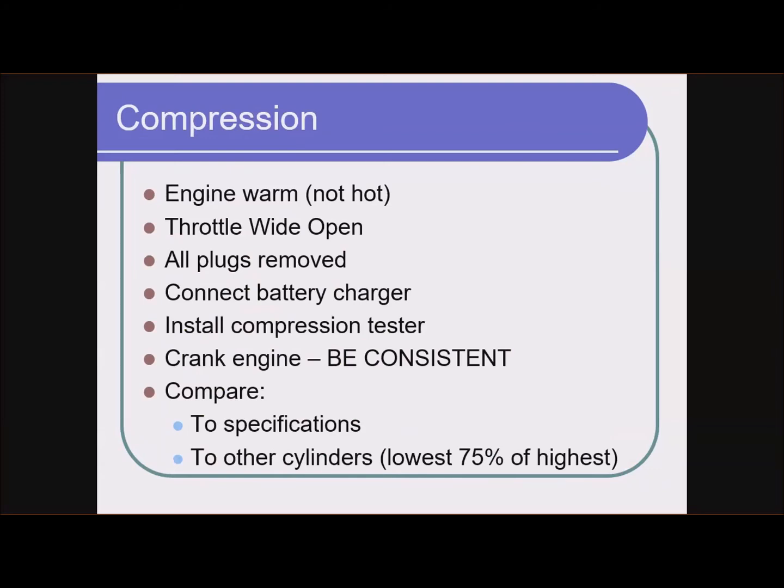So when an engine is at operating temperature, all of the clearances are where they're supposed to be. When the engine's cold, those clearances may be different. So the engine is designed to run most effectively, most efficiently at operating temperature, because that's where it's going to spend most of its time.